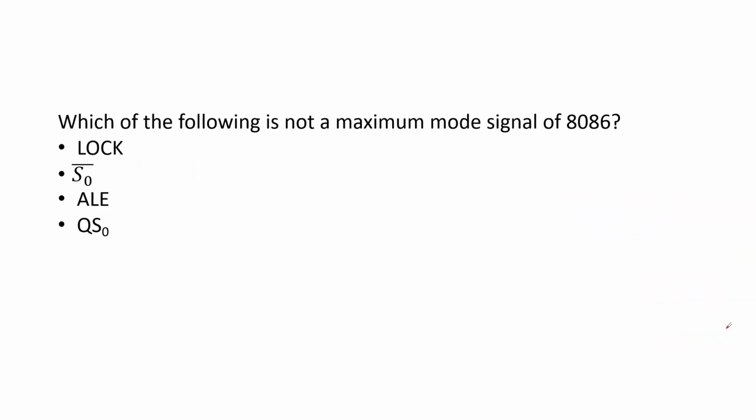Which of the following is not a maximum mode signal of 8086? ALE comes under minimum mode. So the option is the third option, ALE, address latch enable, which is not a maximum mode signal. The other things, LOCK bar, S0 bar, QS0, come under maximum mode signals.